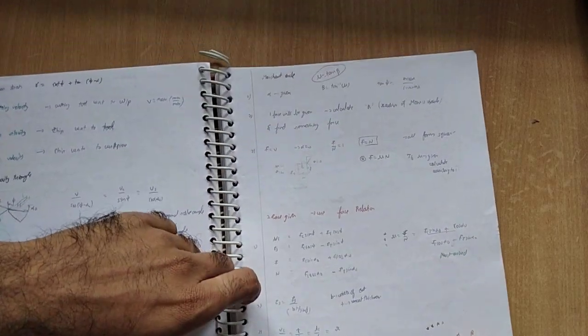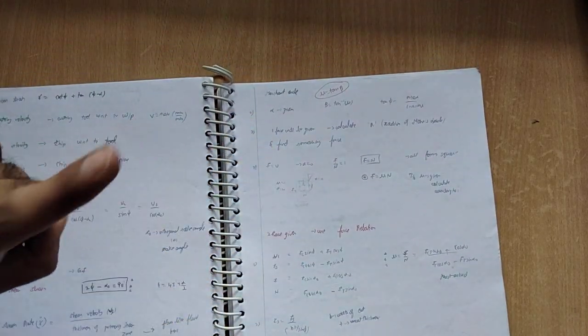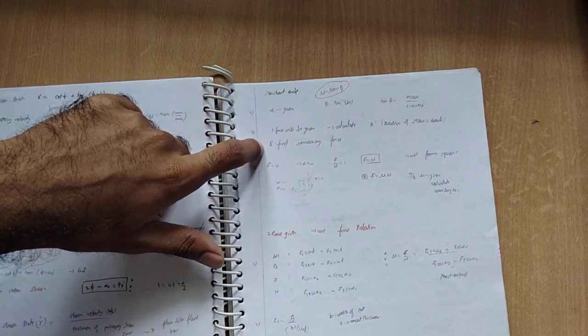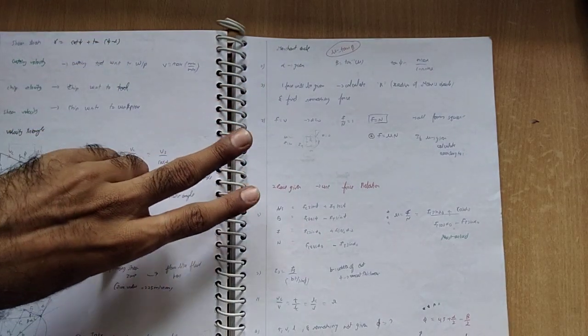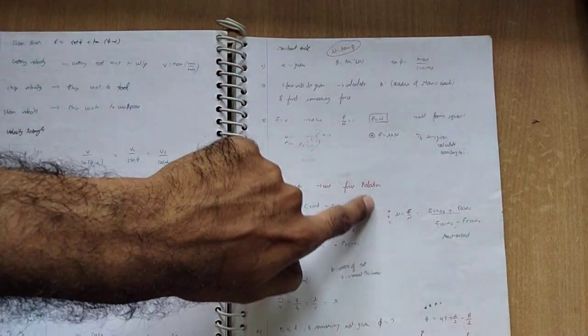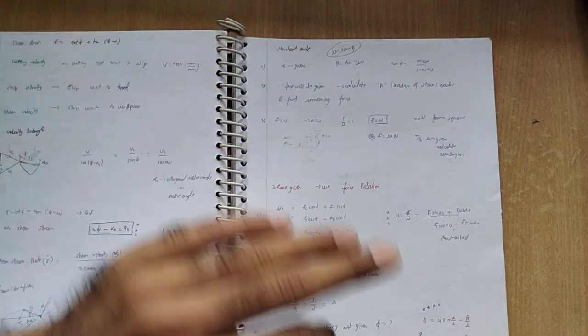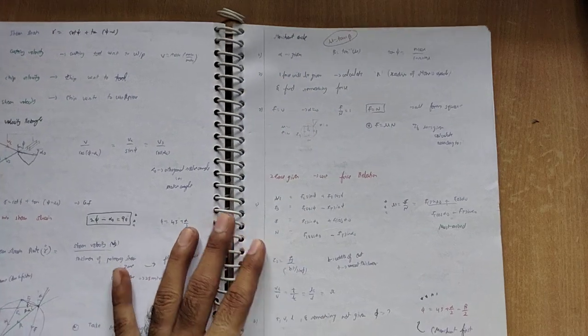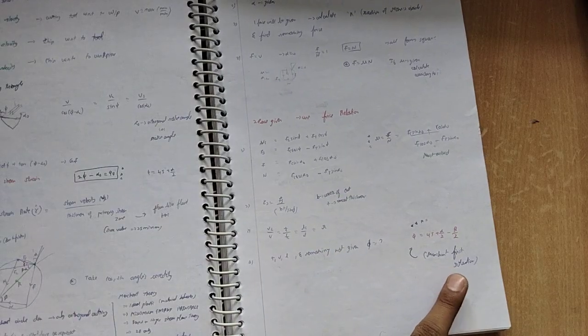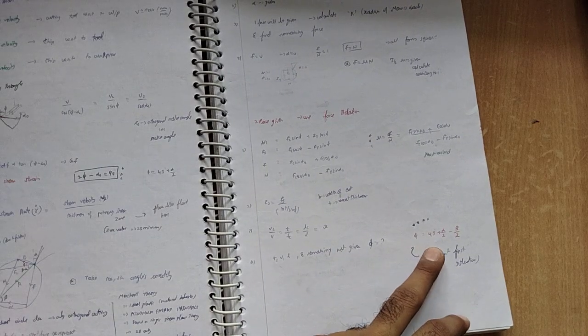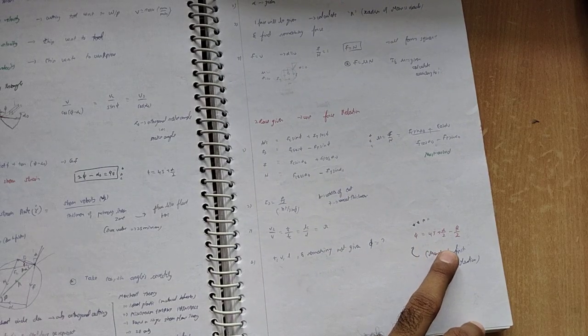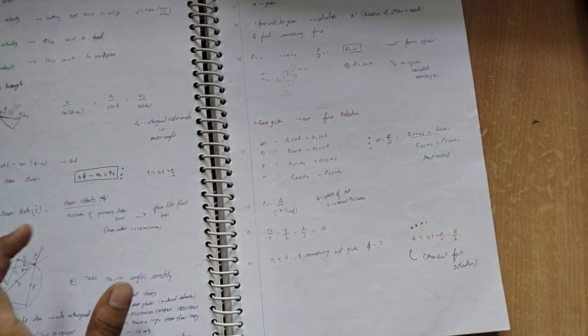It means, guys, until now for the Merchant circle, if they ask one force, we can calculate the one force based upon this. Suppose if they ask two forces, we need to calculate two forces based upon this relation. So different thing, do not get confused. So you can see Merchant's first solution means this is the thing. It means shear angle is 45 plus alpha by 2 minus beta by 2.